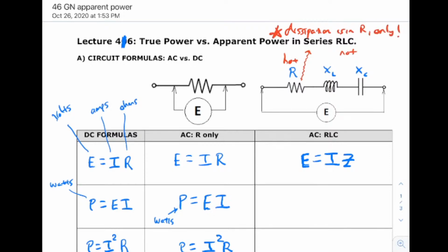Okay, that is a key physical point for this lesson. The resistor only is where you actually lose some of your circuit energy out to the environment in the form of heat. So the coil and the capacitor theoretically are perfect. They're like perfect springs. I don't know how to explain it exactly, but yes, there's a pushback, but the pushback is a magnetic pushback. It's not like in the resistor where it's a friction pushback. Friction makes things hot. Friction you lose, but these are springy. They just push back without any loss. So anyway, you have to use the Z. That's the big thing there.